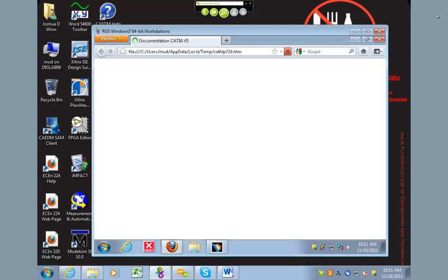And then you need to select a plane. So we're going to make it so that this part is going to be on top of this part. And we'll press OK. And now they've got a constraint. So those will now pivot in one direction, or rotate around in one direction, and they have a connected joint. So you select the faces that are touching? Yeah, I select the faces that are touching.